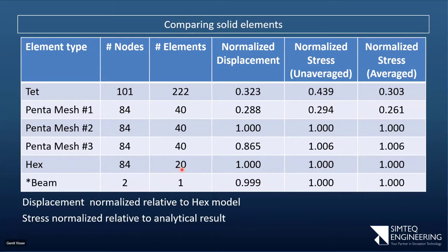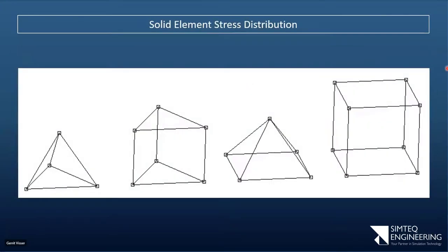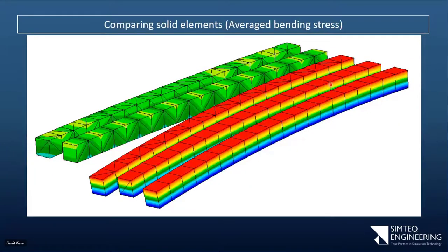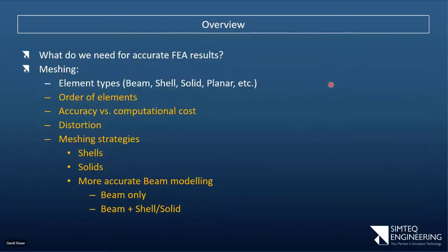In other words, you have a quad, but I've got an internal angle instead of an external angle. You take one of the nodes and you move it way across. Imagine that for a quad. If I take that node and I move it there, I get this weird kind of shape. So with that kind of thing, the element can't solve mathematically anymore. But in those cases, there are usually ways to fix that in any case. Okay, so that's just a couple of side comments I wanted to make about this.